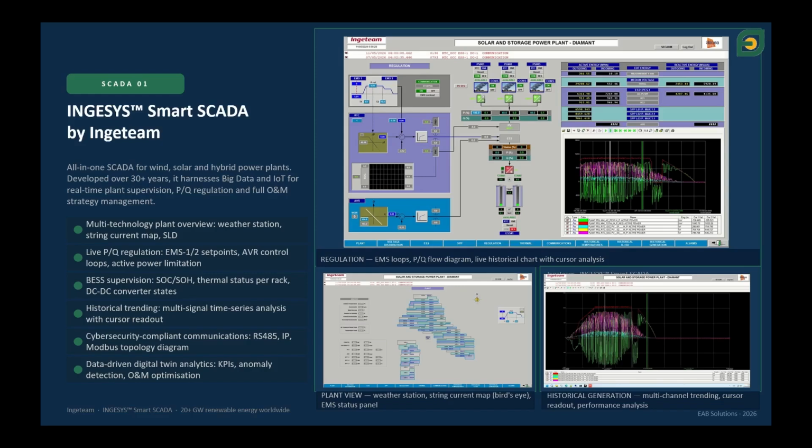Here, what we're looking at on screen is a SCADA made specifically for a project of 2.5 megawatts of PV and 2 megawatt-hours of battery, where the aim was to stabilize PV production, which is considered irregular because when clouds pass or when it rains, production drops suddenly, and the only way to stabilize it is to use a battery to cushion those drops. What you do is charge the battery with the excess energy and discharge it when a cloud passes or when it rains to keep production almost complete. Production much closer to that of a thermal engine or a thermal machine.